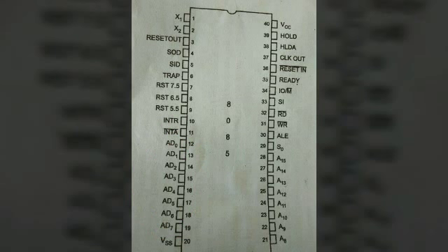During the first part of the machine cycle, these lines are used as the lower order address bus. During the later part of the machine cycle, these lines are used as an 8-bit bidirectional data bus. The lower order address bus can be separated from the bidirectional data bus by the demultiplexing operation using the latch.